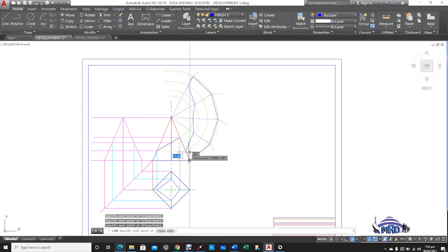So we would have just proceeded then to outline the figure here, and you know, because of the shape, that the lines, the corners must be folded. So this is the stretch out distance, the stretch out shape. We know that the lines must be folded. So at this stage, we can drop in our hidden detail lines now to represent the folding lines for us.